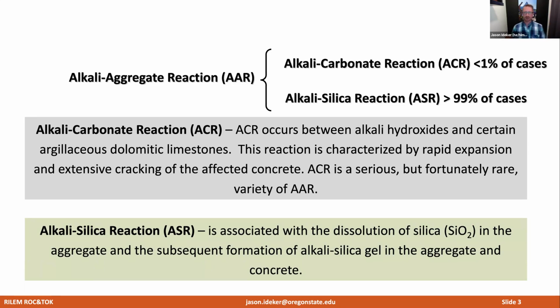Alkali-silica reaction, on the other hand, is associated with the dissolution of silica in and from the aggregate and the subsequent formation of an alkali-silica gel, or maybe a better term is an alkali-silica reaction product that forms within the aggregate, and eventually as it cracks the concrete apart, that alkali reaction product will continue to work its way throughout the entire concrete matrix.